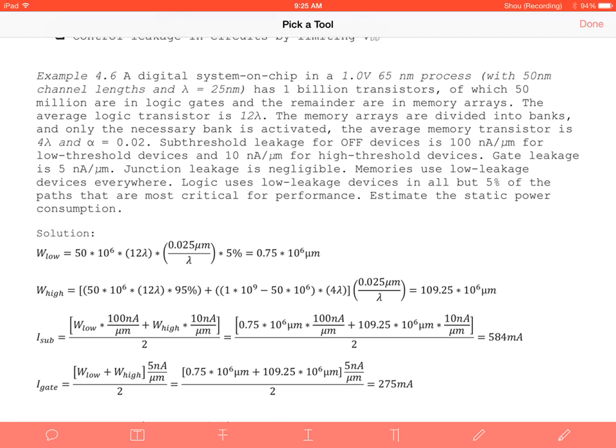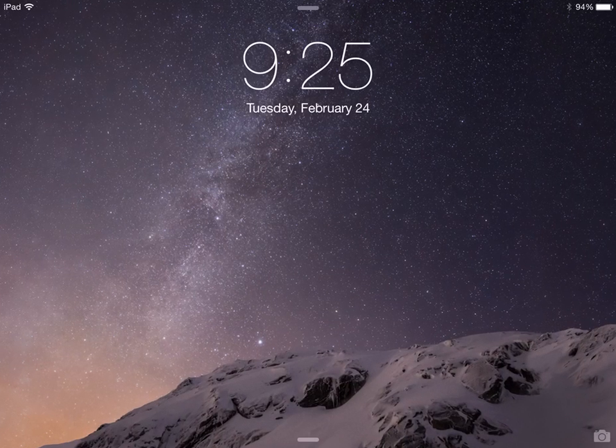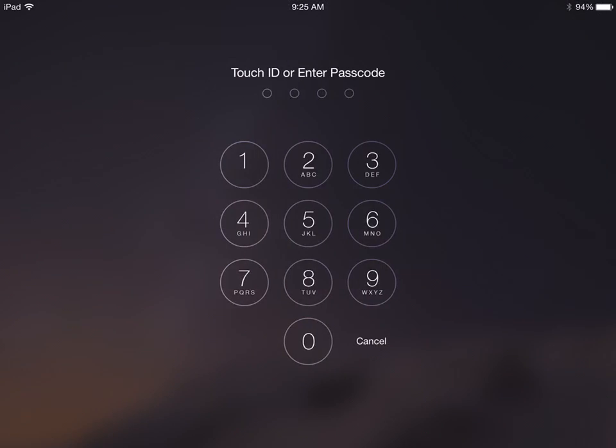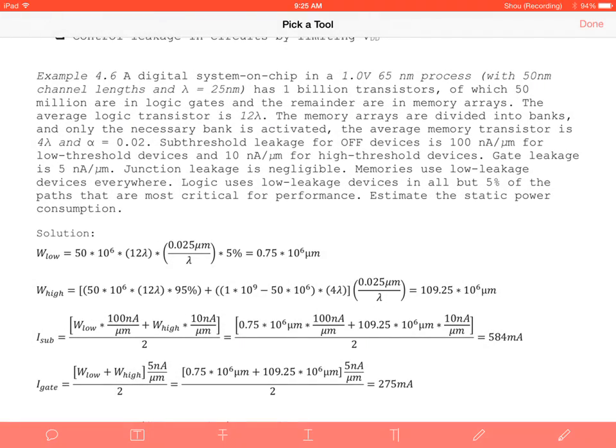So in memory devices, SRAM, DRAM, which we'll be learning about in the next section, low leakage devices are very important because you want to save your information. Don't they have refresh? Mm-hmm. Yeah, DRAMs in particular, you have to worry a lot about constantly refreshing. In DRAM, you have a signal every clock cycle and some sort of loop back, and it's a sequential element, and you're going to be refreshing it.